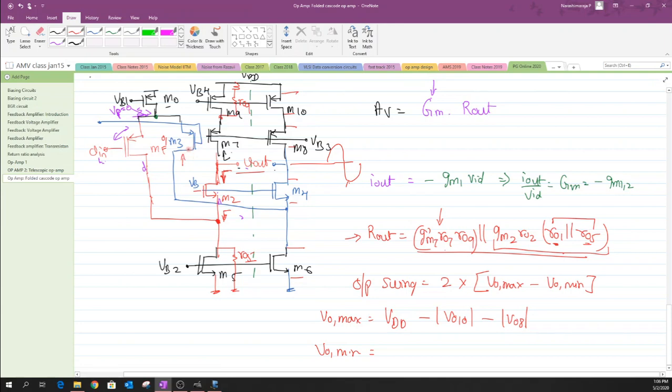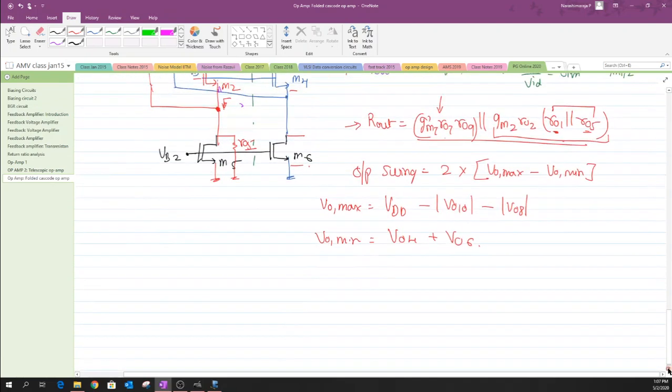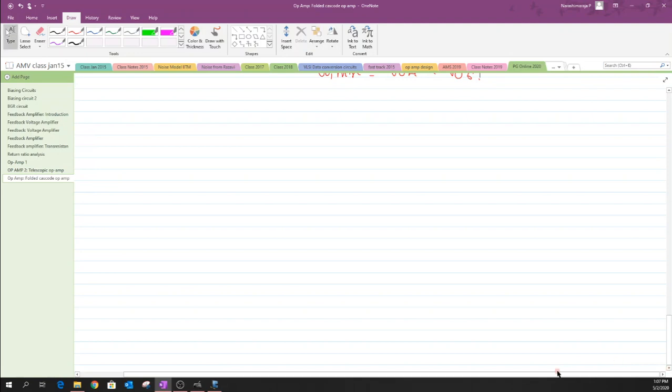Okay, but in short, it doesn't. It only impacts the drain and source of M6 and M4, and it never impacts the drain and source potential of M3 when we have a lower swing here. So the minimum voltage swing that one could have across the Vout can be written as VOV4 plus VOV6. Yeah. So with this basics, let us move on to the problem. Let me just copy this problem.